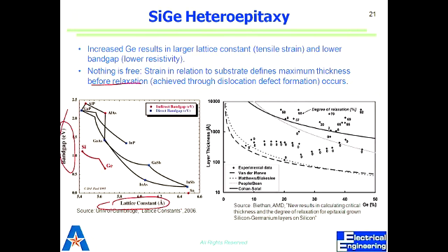So this tells us that once you go from indium antimony to gallium antimony, your band gap is changing. This is your band gap in electron volts. From somewhere around 0.18 it can go to close to 0.8, which you can't do for pure material. But with epitaxy, you can grow material in different fractions and change the band gap.